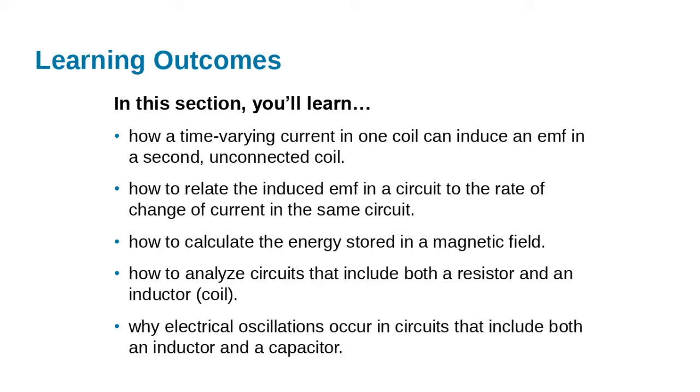Okay, so the learning outcomes for this topic: you'll learn how a time varying current in one coil can induce an electromotive force in a second coil that's unconnected to it. And you'll also learn how to relate the induced EMF in a circuit to the rate of change of current in that same circuit.